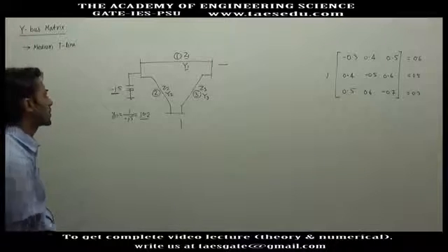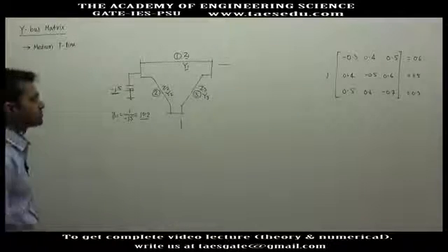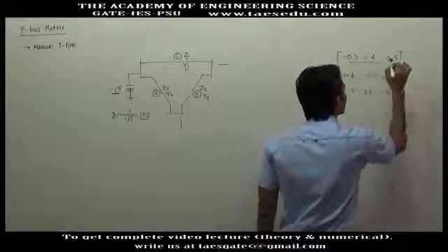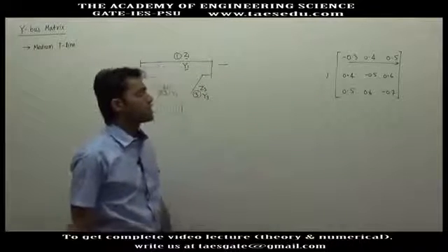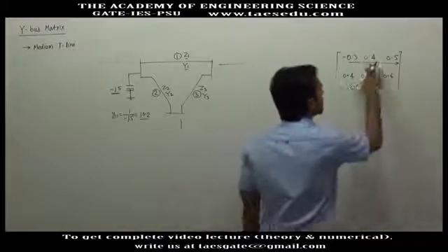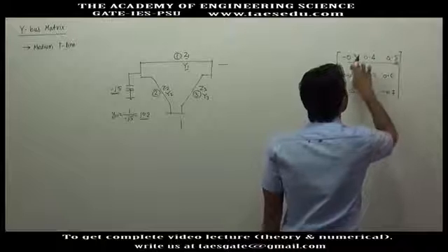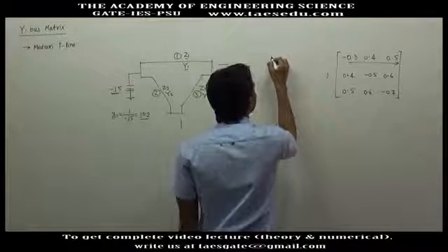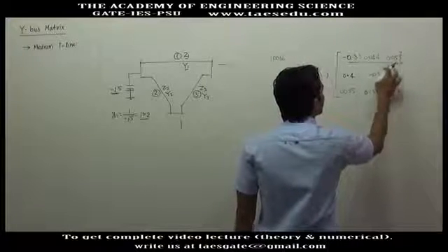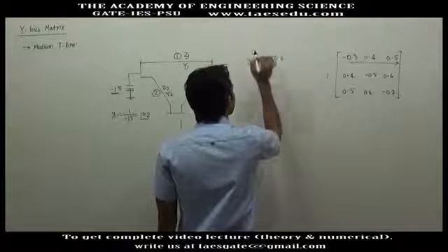Okay. Now to calculate the parameters of the transmission line, we will use the bus admittance matrix. Now if you add all these 3 elements, what do you get? The overall shunt parameter of bus 1. If you add it, you will get j0.6. And what is this? The overall shunt parameter of bus 1, and I represented it as Y11 dash.